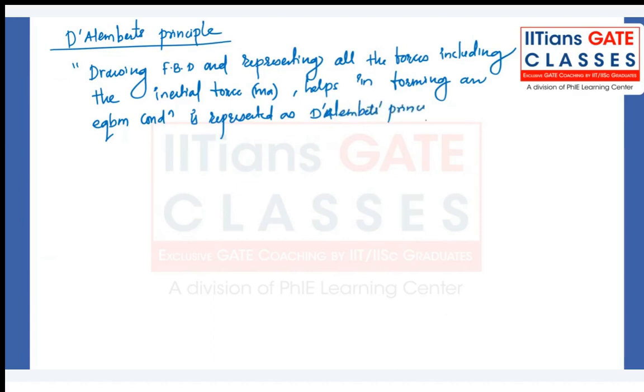Yes, Abhishek, the summation of y we can anyway do because the body is not moving in the y direction, so weight is equal to the normal reaction. Suppose friction is acting, then in the previous example, P is acting in the rightward direction, and minus mu times N is the frictional force in the leftward direction.